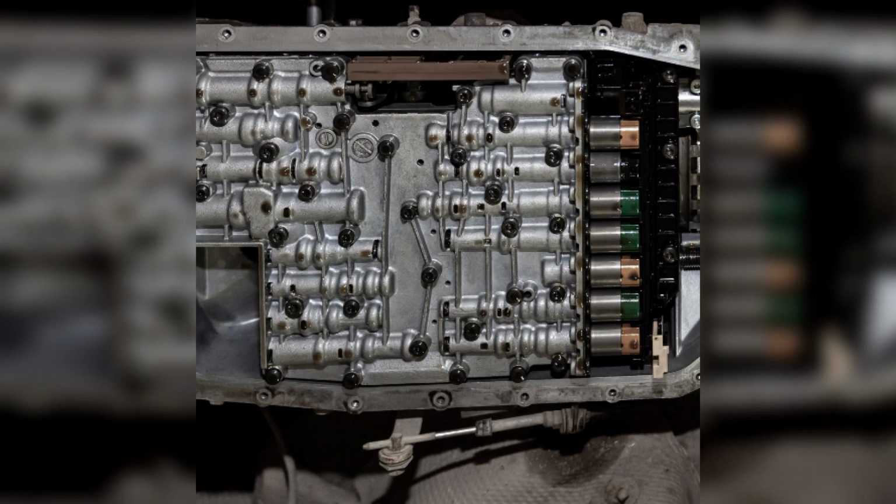They manifest themselves in the form of bumps, jolts, automatic transmission going into emergency mode, jerks when shifting gears. As soon as you notice when driving your vehicle with automatic transmission that the gear shifting is performed with jolts, this is a good argument to check the solenoid unit.